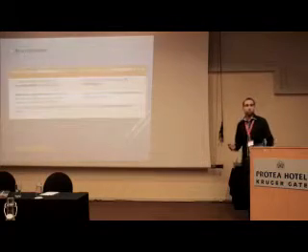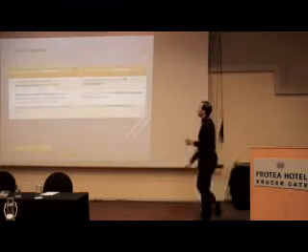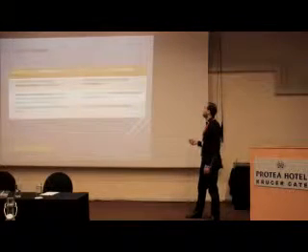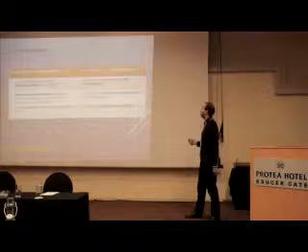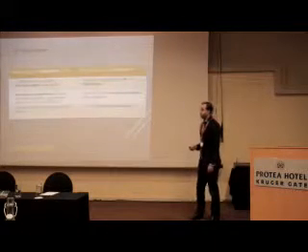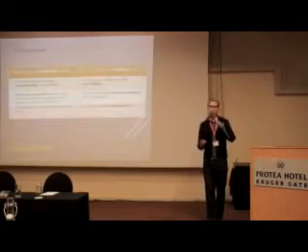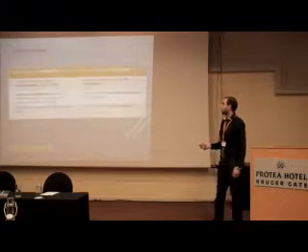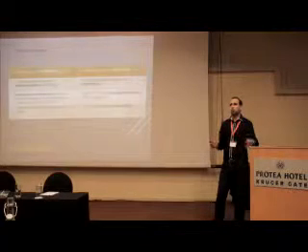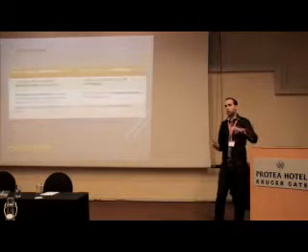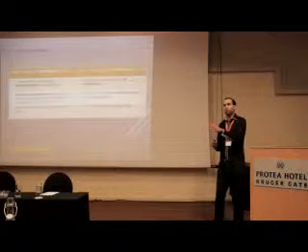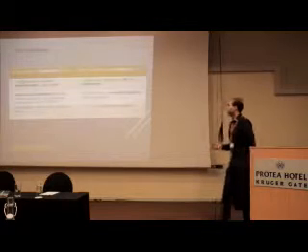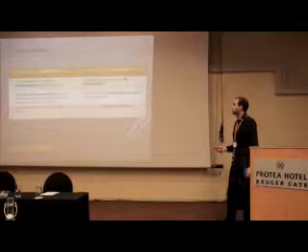Okay, so as a conclusion, I will just make a small summary about advantages of this board, this FPGA, and disadvantages of this FPGA for software-defined radio. The most important thing about FPGA is the reconfigurability. This is very powerful for software-defined radio. It means that if you want to change one frequency at each step of your project, you can do that using FPGA. The second advantage is the reduced component cost.